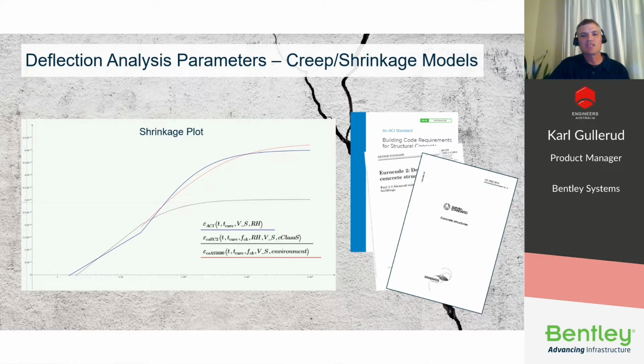Note the significant differences, especially with the Eurocode 2 model. When using a software application for refined deflection calculations, then, it is important to understand which models are implemented, and if the one in your design code is not implemented, how the available models might differ from the one that is required.